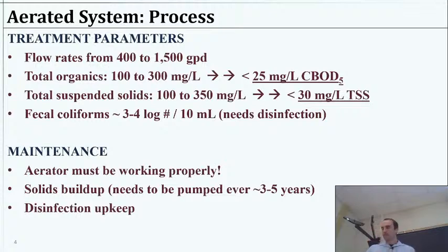So 5-day biological oxygen demand, coming from the carbon. And 25 is still a fair bit. So if we compare that to wastewater discharges in other places, this is probably over the limit of a fair number of municipal discharges. It kind of depends on the receiving water. Sometimes you'll have two limits. One, you might say it must be like 90 or 95% reduced, and it has to be below 10 milligrams per liter, something like that.